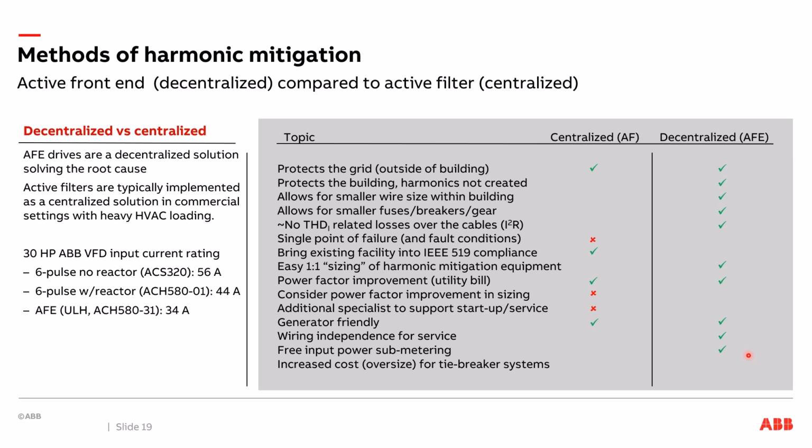So if you look at all your different air handlers, all your different pumps, all your different VFD driven equipment, you don't need to buy a bunch of separate submetering power meters. You just look at that information over, say, Modbus or BACnet, and that information will all be freely available over the drive's communication protocol.